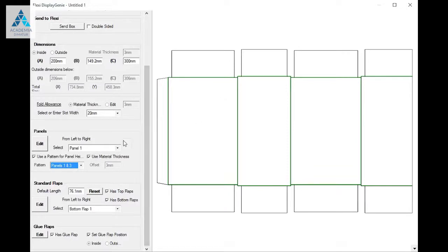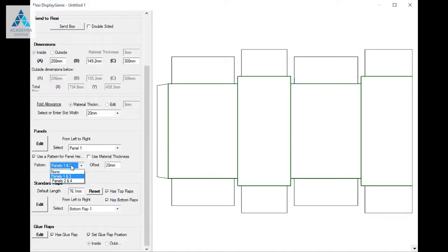And then the next thing that I want to show you is that I can change this material. Let's make it 20 millimeters. Now you can really see how that line is joined around like this, so that your tool will take one tool path for this whole thing.